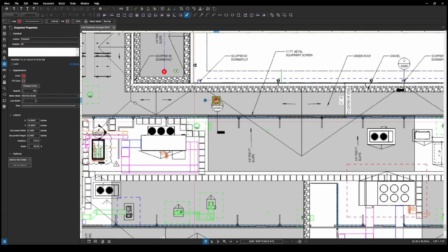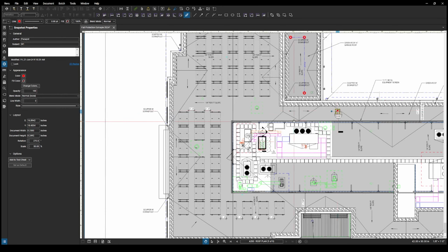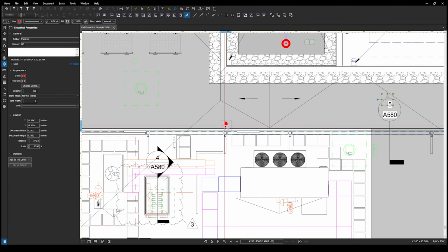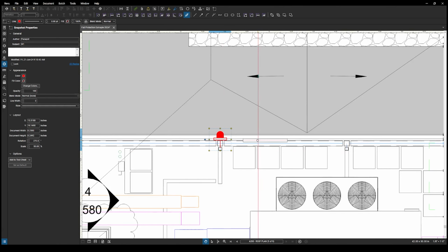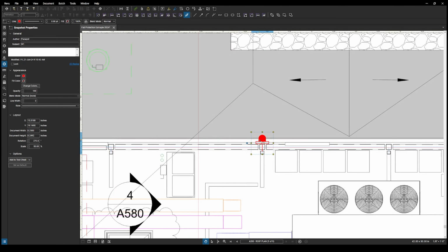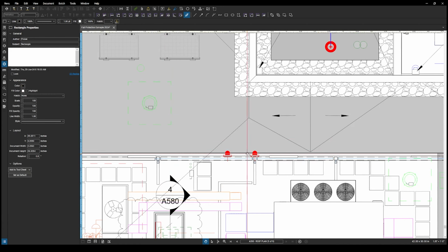But of course, doing something like that is also going to come with a few little intricacies and quirks here and there. So first thing we've got to do is figure out any elements that we can use, like a screen wall, which this drawing does have, which will allow us to offset the amount of wall anchors they would need. And that's also going to reduce the penetrations in the roof system with those anchors, which is going to minimize any potential leaking or just really cut down any kind of rooftop problems, structural things, stuff like that. So the more we can prevent penetrating the roof, the better.